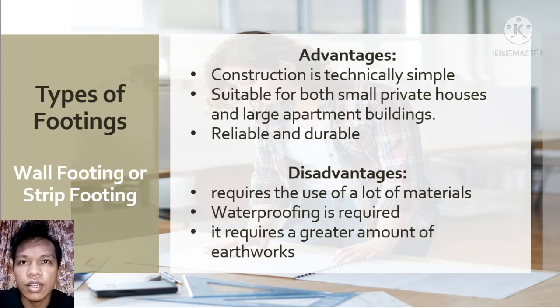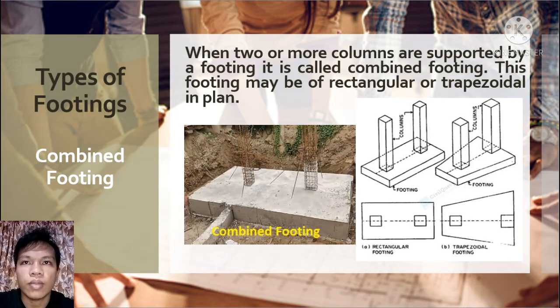And these are the disadvantages. Strip foundation has a number of disadvantages as well. Building a strip foundation requires the use of a lot of materials. Waterproofing is also required. If the above-ground structure to be built is massive or intended to have a basement, it requires a great amount of earthworks.